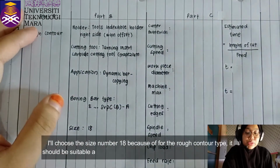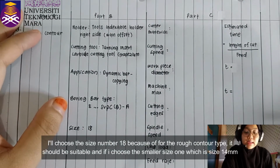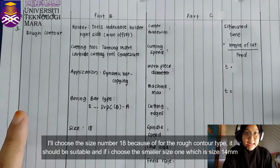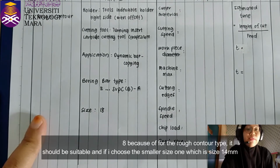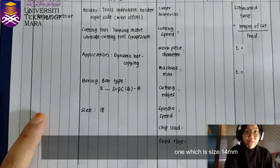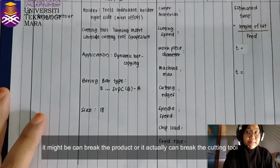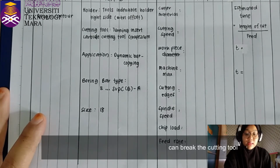I'll choose size 18 because for the rough contour type, it should be suitable. If I choose the smaller one, which is size 14 millimeter, it can actually break the product, or it can break the cutting tool.